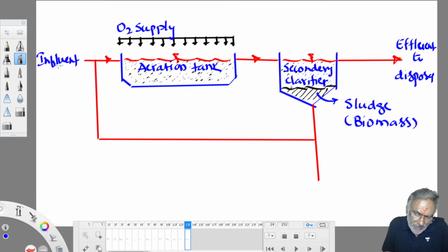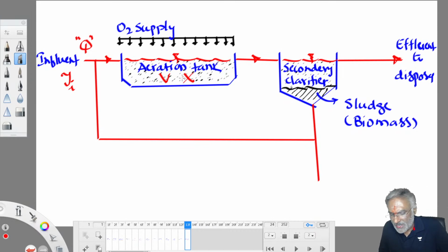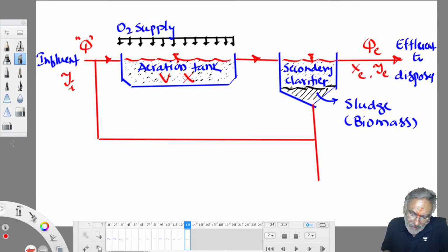So this effluent from primary treatment becomes influent to secondary treatment. Okay. So here Q amount of wastewater with BOD YI is applied into V volume of aeration tank with concentration of organisms X. Out of this, QE amount of effluent is disposed. Not all organisms settle down, some organisms escape also. The organisms that escape are XE with BOD Y. All of the food is not consumed, some food they left unused also, that is gone out.